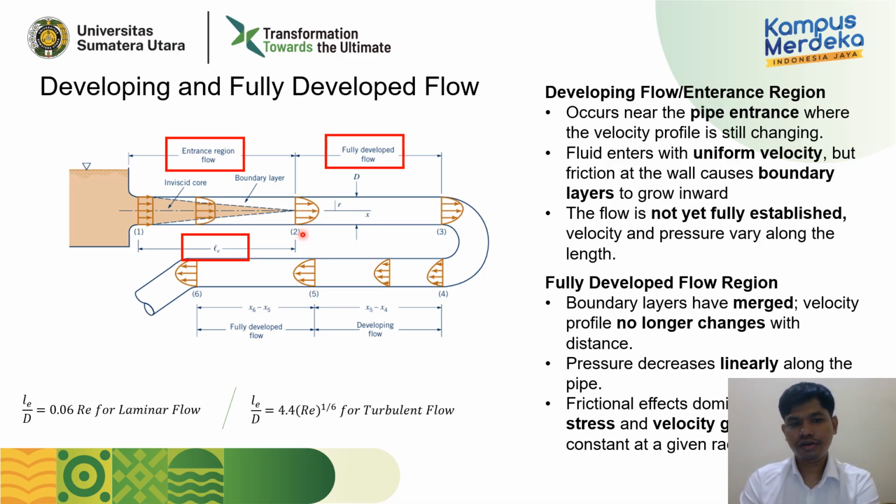You can see here the velocity profile is similar after the fluid flows past the entrance regions. At the fully developed flow, the pressure decreases linearly along the pipe. Later I will show you the pressure decreasing linearly inside the fully developed flow.